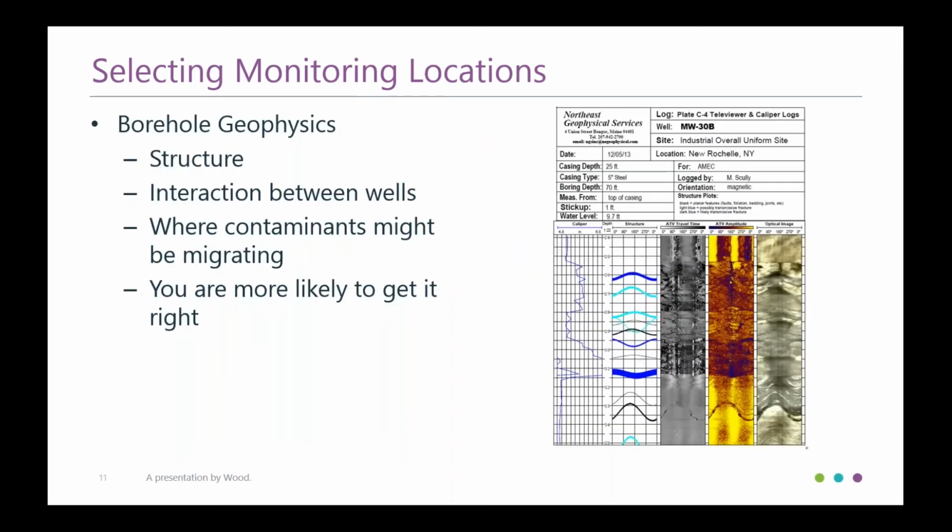So when you're looking at borehole geophysics, what you're looking at is the structure of the bedrock. Do you have fractures that might be important and transmissive? Do you have interconnection between wells? You can start figuring that out when you start doing the borehole geophysics. So you're doing several evaluations in the borehole.